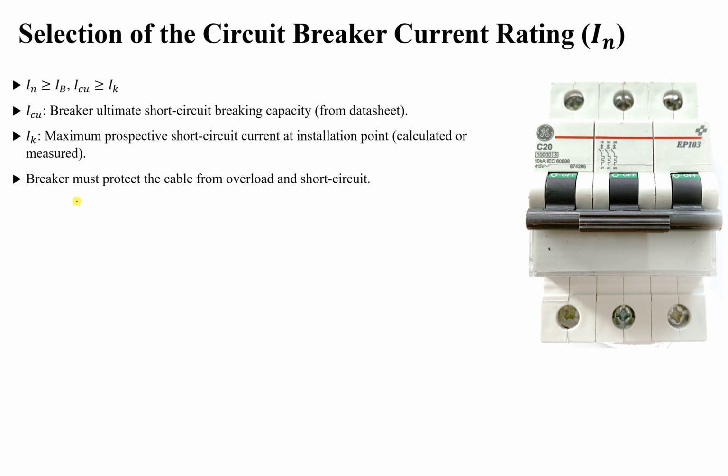So the breaker also must protect the cable from overload and short circuit. Now this will change if we have other loads, this is for static loads.